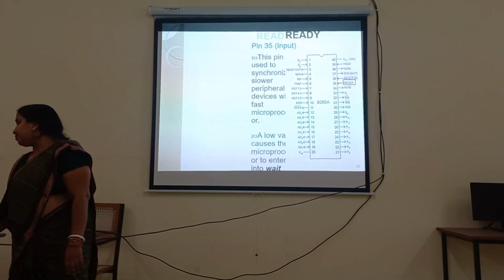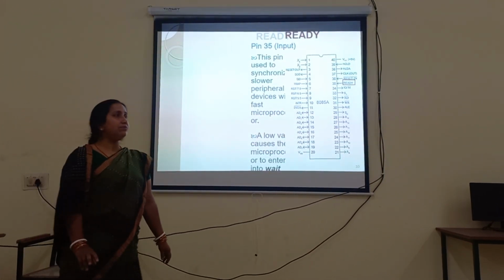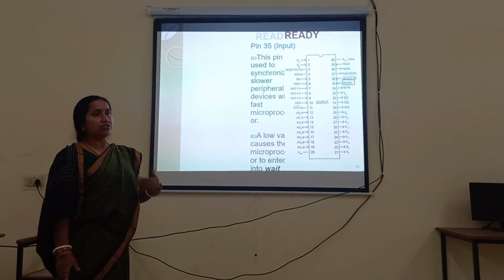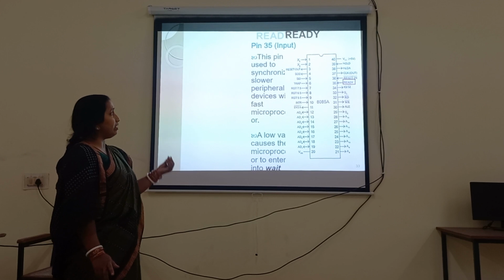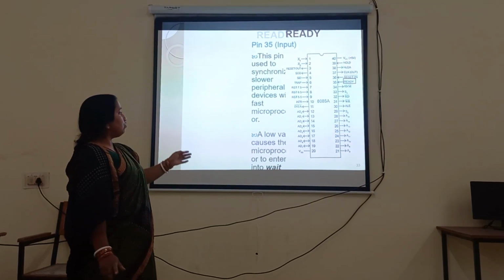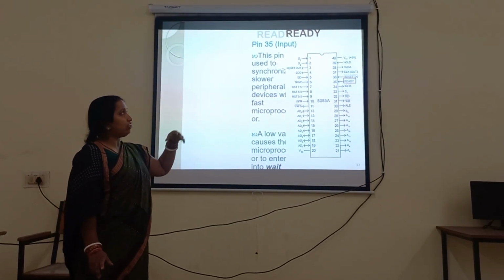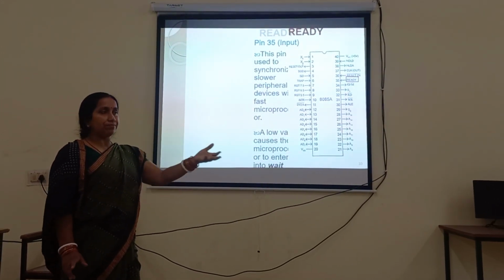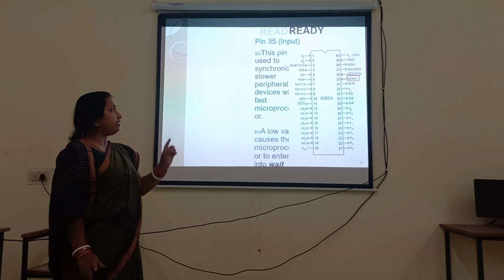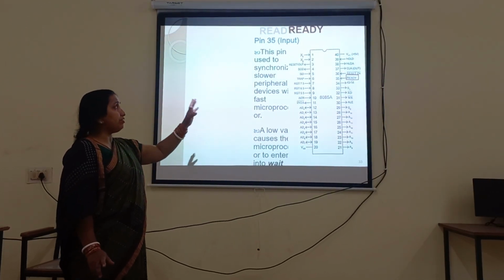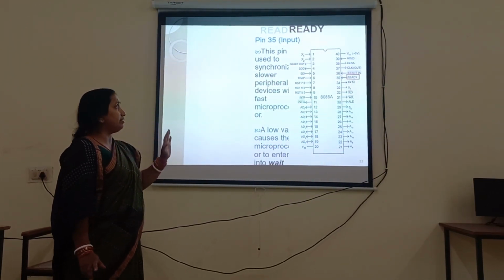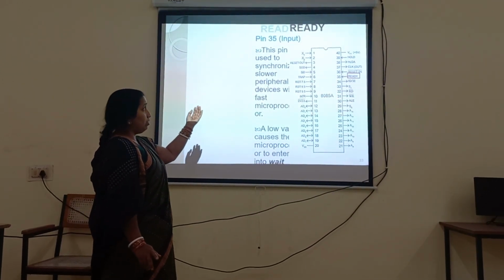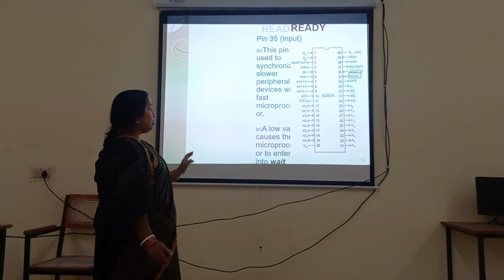So the next one is the ready signal. Ready means the microprocessor is in operation state. We indicate it by an active high signal. When a peripheral device is attached to the microprocessor and the microprocessor is ready to work with the I/O device or memory, it indicates by the ready signal going high. That means the peripheral is keeping pace with the microprocessor, and the low signal